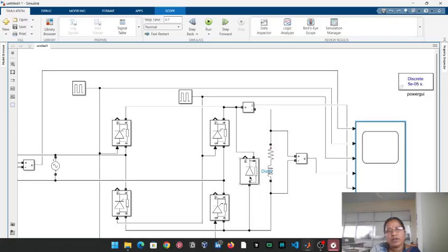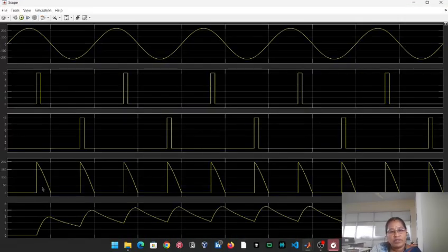This diode conducts every half cycle, from pi to pi plus alpha during the positive half cycle, and during the negative half cycle from 2 pi to 2 pi plus alpha. See this waveform. Here the triggering alpha value is 120 degrees, that is greater than 90 degrees. From 0 to 120 is the delay, this is alpha. From alpha to pi the thyristors conduct, from pi to pi plus alpha the freewheeling diode conducts and discharges the reverse voltage. So it looks like the R load output waveforms.